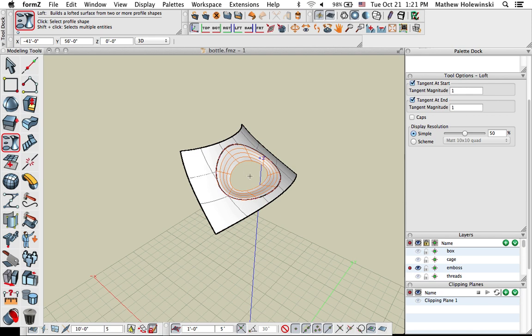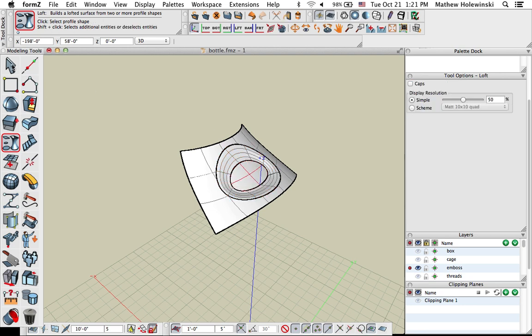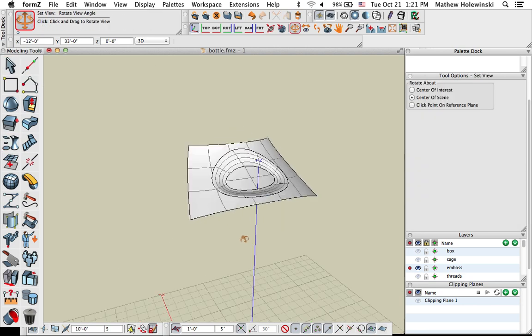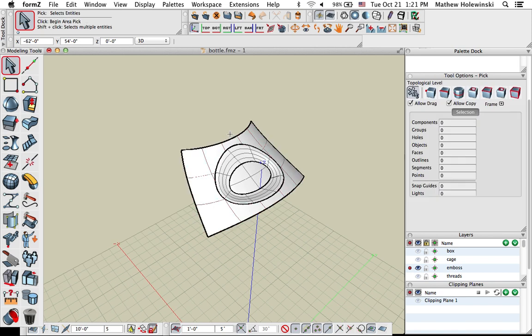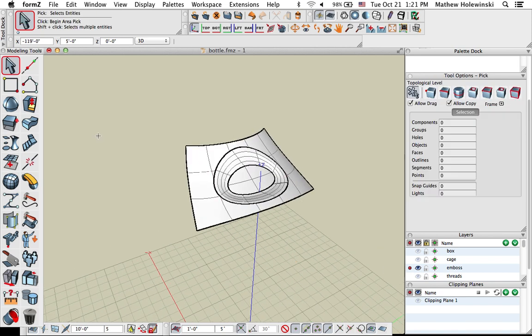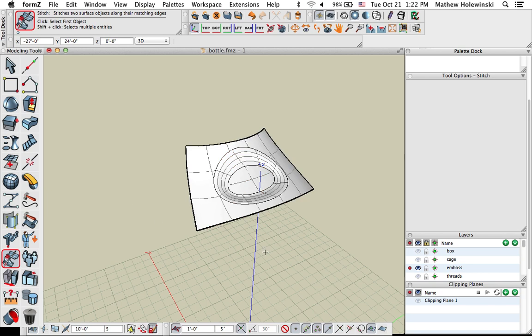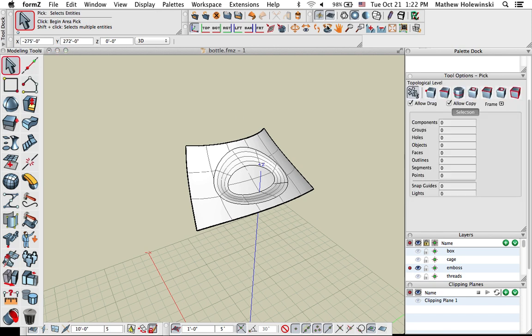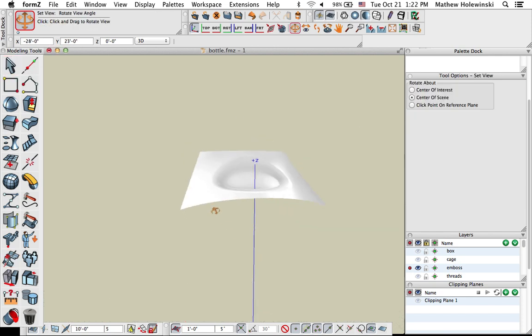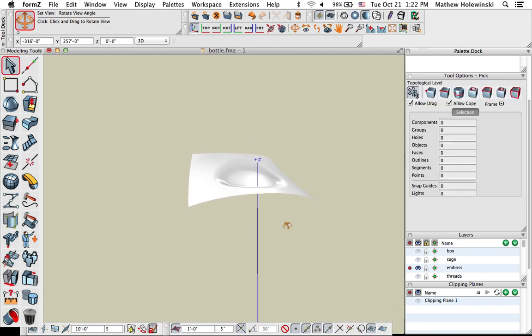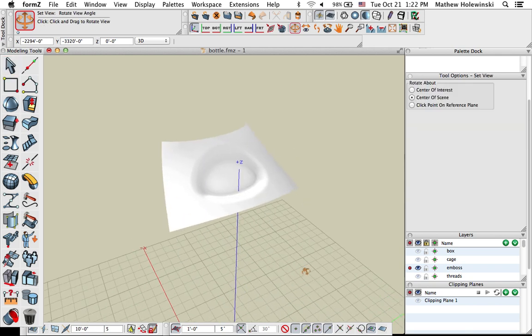Now, when you click the whole surface here, it does ghost it. So I did a copy operation, so I'm going to paste that back in there. That's just the nature of the ghosting inside of FormZ, standard stuff. But anyways, we have all these pieces now, and you can see if I were to do a Command A, I can actually stitch those back together, and so they actually fuse them all together, and the stitch operation is going to make that one single object now. So there we have a nice little embossed type detail that has been added into that surface.